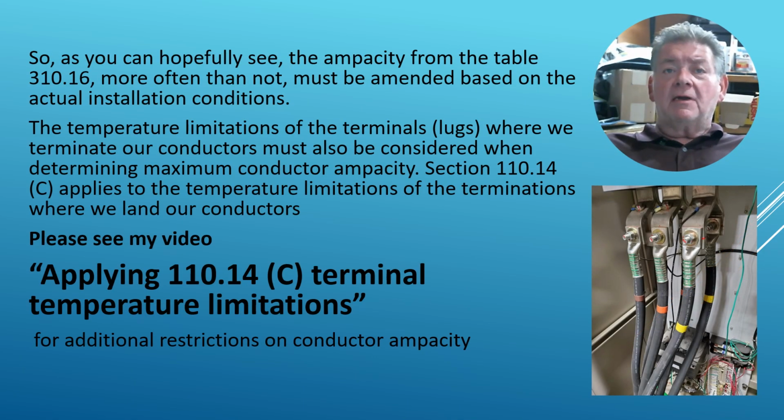So, hopefully, as you can see, the ampacity from the table, more often than not, must be amended based on the actual installation conditions. You also have to consider the temperature rating of the terminals or the lugs where you land your wire. The temperature limitations of the terminals or lugs where we land our conductors also must be considered when you're trying to determine the maximum conductor ampacity.